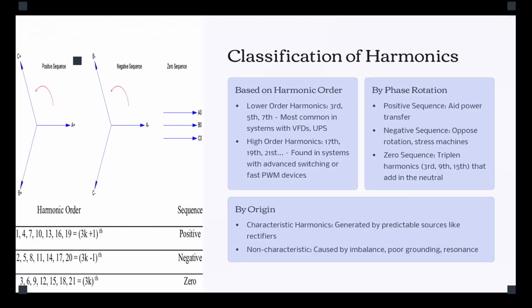Okay, so now in the third harmonic, sixth harmonic, ninth harmonic, and all the multiples of three, all the orders that are multiples of three would scale that 120 degree phase shift with the same order. So eventually the summation would be zero, so we don't have any rotation.